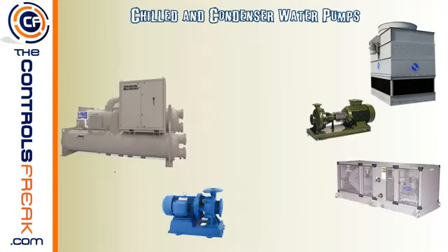We've already talked about the chiller here, and we've also talked about the cooling tower. Some other little items besides the pumps that we put here is the air handler. This is an example of a packaged unit air handler that would be inside the building, and you'll see the little pipe connections here, and that's the cooling coil that's inside the unit. This green pump is going to represent our condenser water pump, and typically they use green piping or green to represent condenser water. And then this little blue pump here is going to represent our chill water pump, and they usually try to use blue or white for chill water piping as well. What we're going to try to do now is connect the piping all together, and see if I can get some colors here.